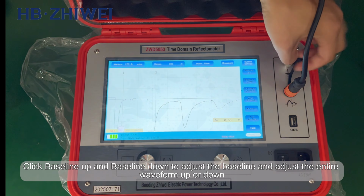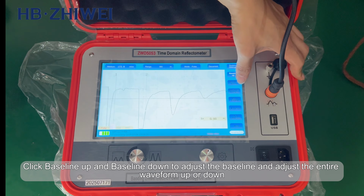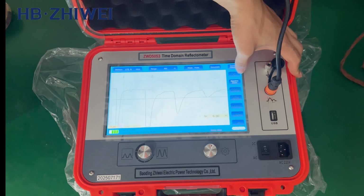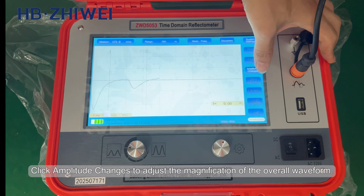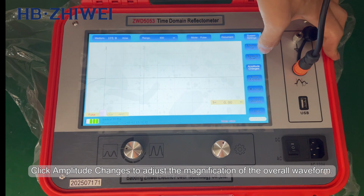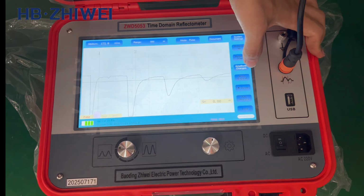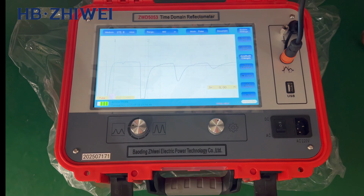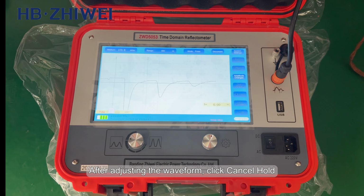Click baseline up and baseline down to adjust the baseline and move the entire waveform up or down. Click amplitude changes to adjust the magnification of the overall waveform. After adjusting the waveform, click Cancel Hold.